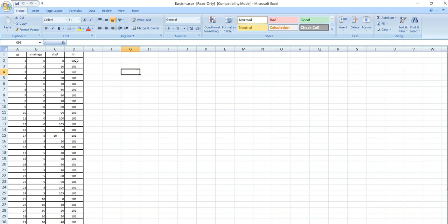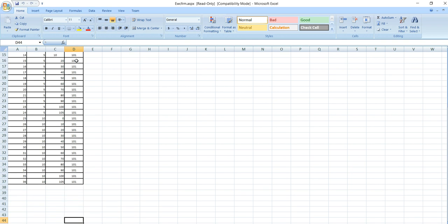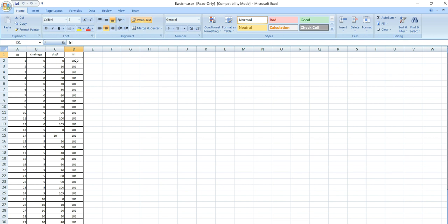That is, we want to have the uniform level of 101 meter. So we are keeping FRL 101, like that. For the entire complete area, our reduced level is 101 meter. So like this, you have to keep your input data, for the existing RL and final RL. So connect the 2 files, and you can proceed with the application, and you will get the result finally. So let me close this file.